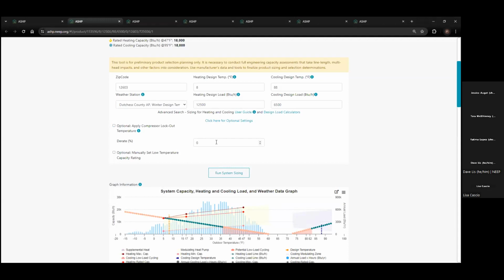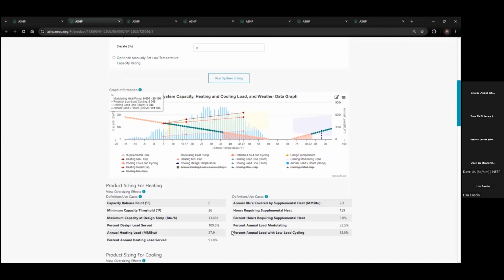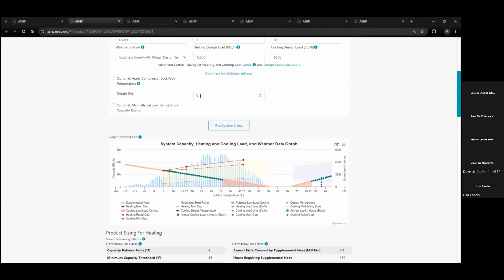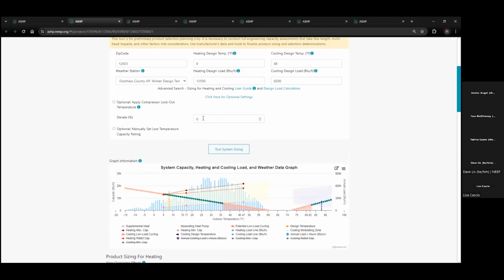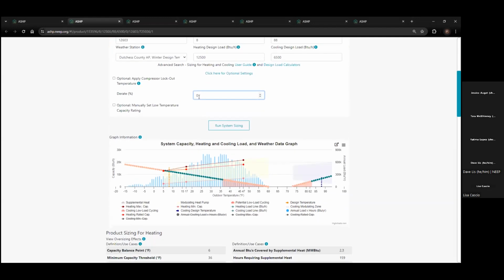The D-rate percentage affects the annual load that is seen by the piece at that location. It is meant to account for some solar heat gain of that home and zone. The default value of this is 10, so if you enter 10 in here, these values should not change. If you want to increase that, say you have a home with a lot of glazing, maybe west facing and it gets a lot of heat from the sun, so at temperatures of 40 degrees you still get some nice sunny afternoons, you can up that D-rate percentage to whatever you like.